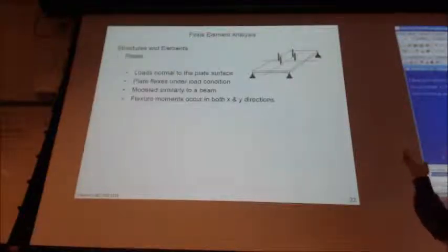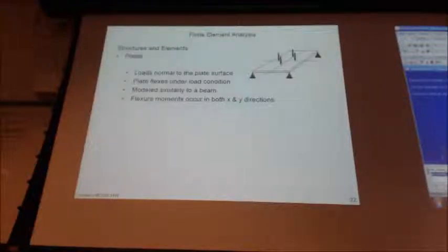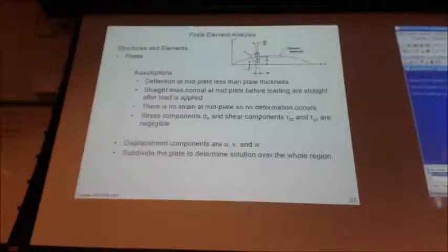Plates are another element where, the reality is when you get to the bracket for Jeff's project, you're not going to apply a plate element to it. You're just going to 3D mesh it and go, right? But if we know and understand what some of these other things are doing, then it helps us analyze the results so that we're not just buying into the results.